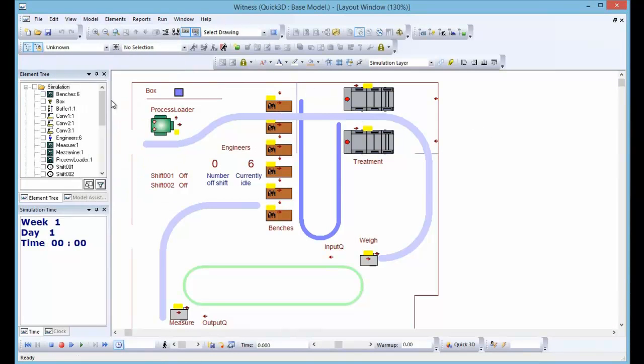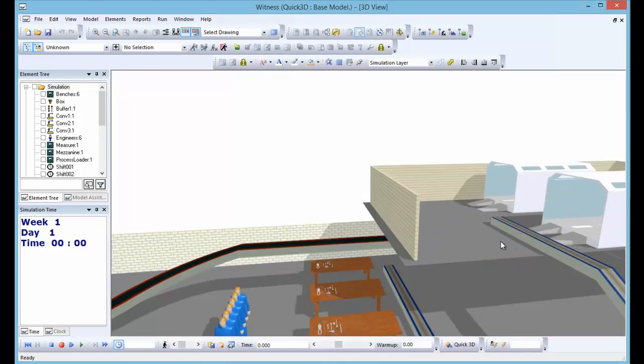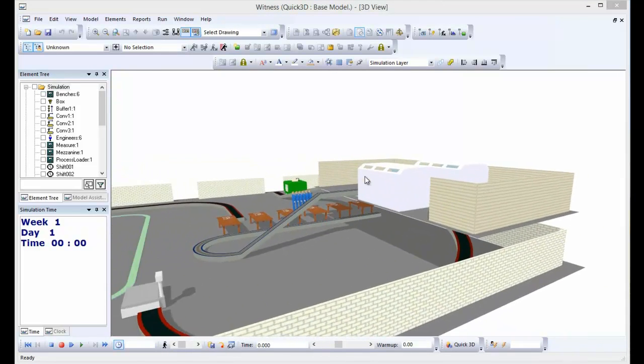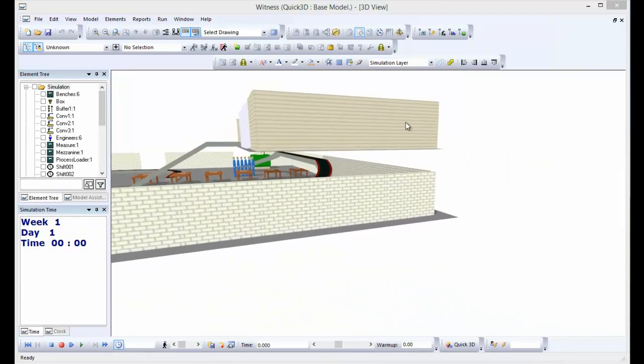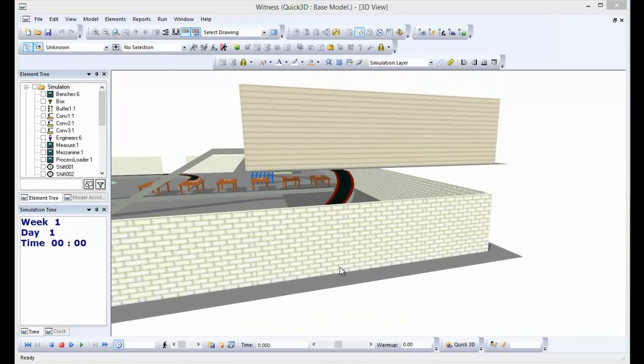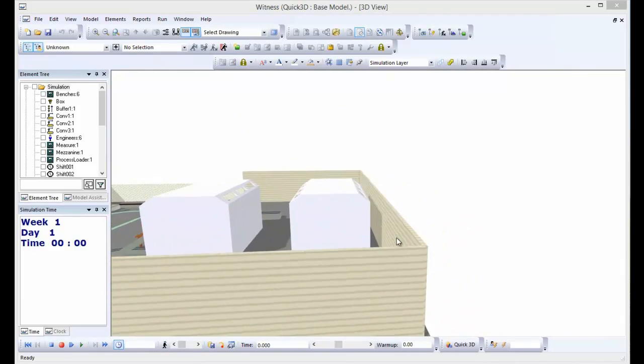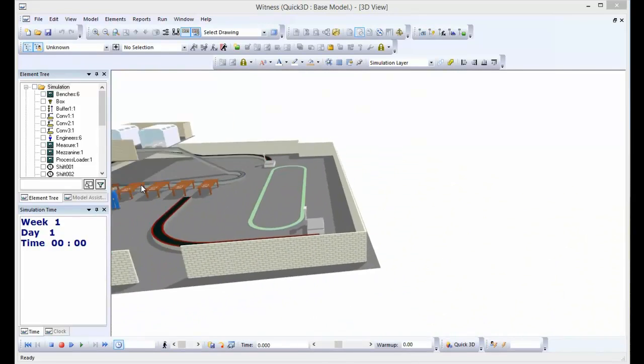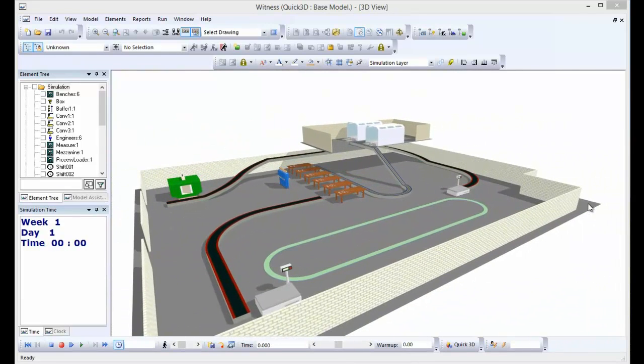Because they're extruded to a height of 2 distance units, we know floor 1 here is at the height of 3 distance units, and that seems to tie in very well with what we see here. We see the one layer extruded up to a height of 2, then a gap of 1 meter to the next floor, and then another height of 2 meters in the different texture that's drawn. You can also extrude rectangles and ellipses. Ellipses can be, of course, a good way of doing columns, and they will extrude in a solid form with capped ends.